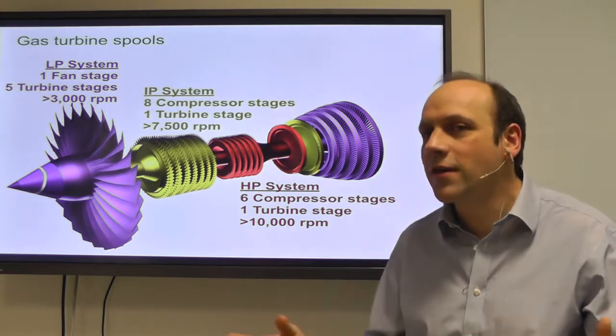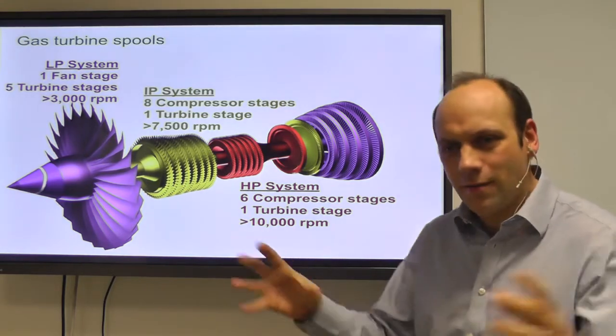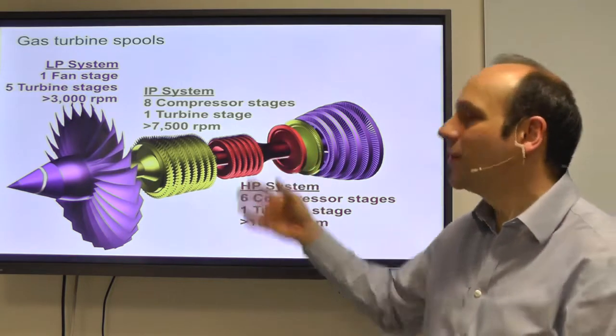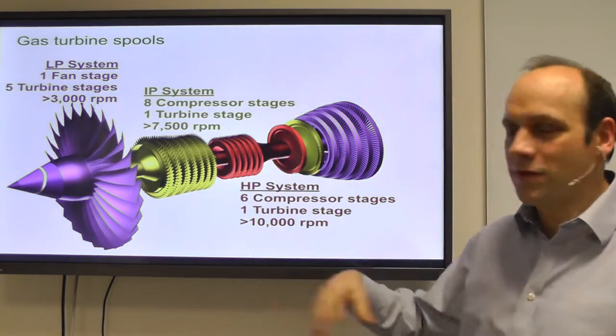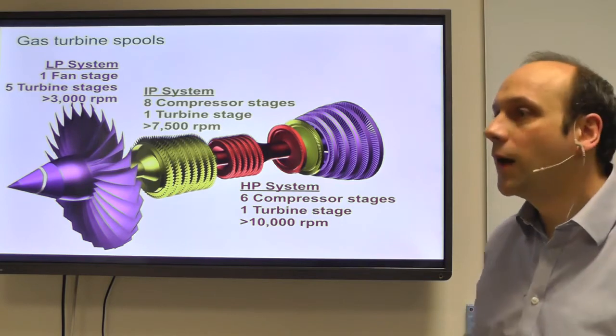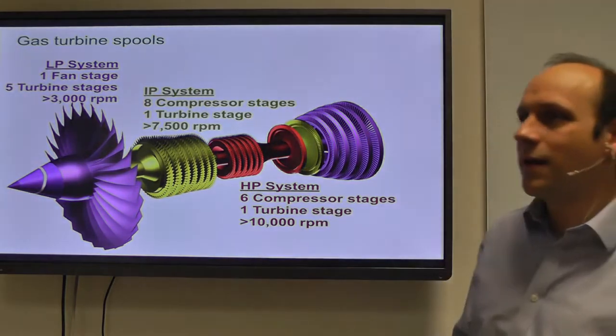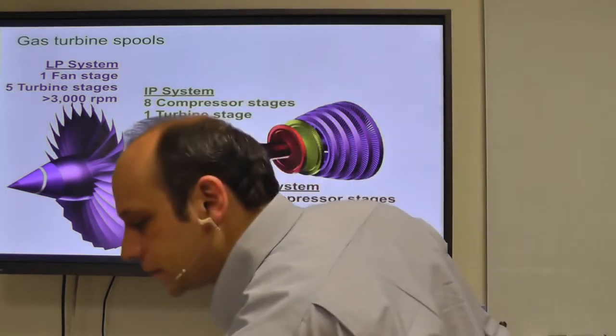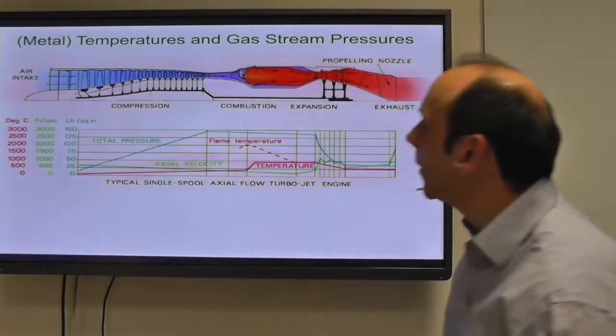Turbochargers get up to 100,000 RPM, but they're much smaller. And small jet engines spin very fast, but big engines, you're limited by things being supersonic and by the sort of centrifugal forces you can handle. And that means you're at a mere 10,000 RPM, but that's still pretty fast, right, for a big structure. So that's a big number.